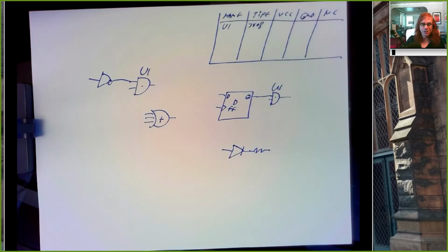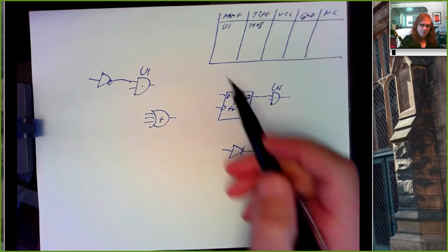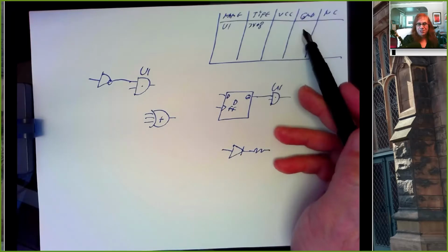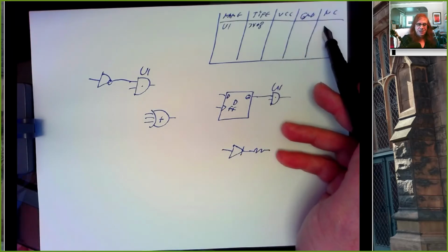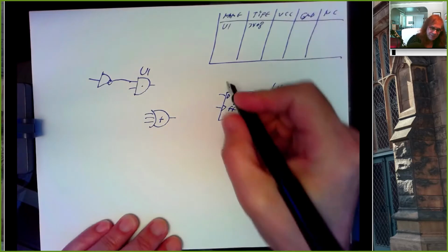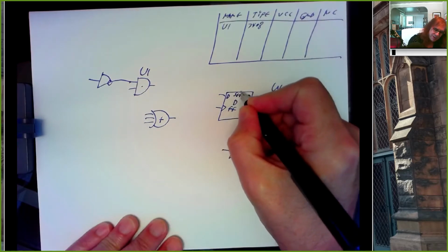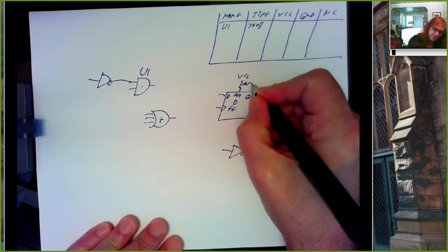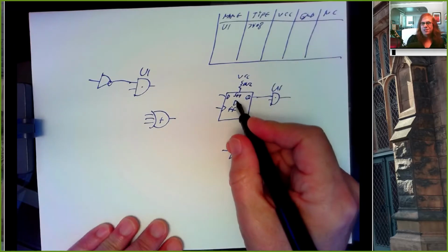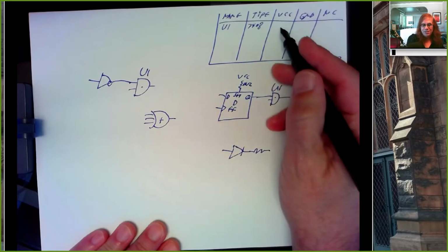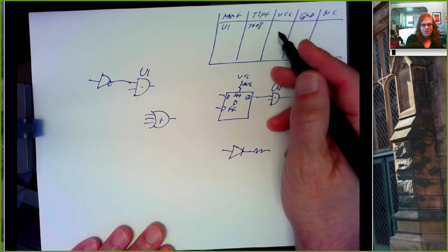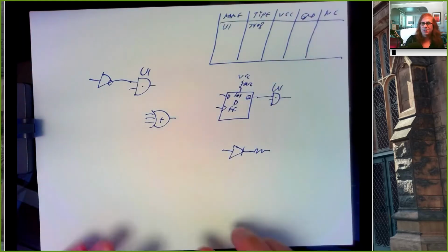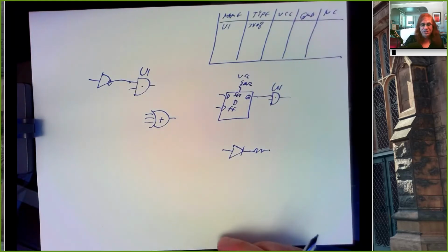Component ID block is really just showing, when you have the symbol, what kind of chip is it, where's the power and ground connection, and which pins don't get connected to anything. For example, here's our set pin, and our set pin needs to go through a resistor to 5 volts, right? And I don't forget which pin this is, it's either 1 or 4. Don't put that up here, that's not a power connection. That's an input that you want to set to logic 1, but that goes in your schematic diagram, right? This is just detail here.